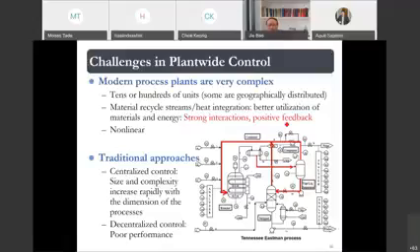Now, the modern plant-wide systems can be quite complex. Often they have tens or sometimes more than a couple of process units. And I just now mentioned the material recycle streams and heat integrations. They're very good to make better use of materials and energy. But from a control point of view, that's bad news, because they actually introduce positive feedback that leads to strong interactions among process units.